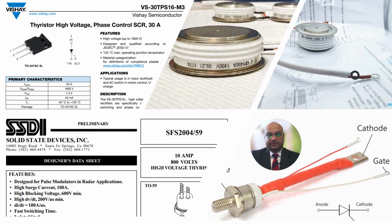Now let's see some of the data sheets, or how these thyristors look. As we have already seen, it can be a 3-terminal device as represented here by a make which is Vishay Semiconductor, and it is available in the form of 1600 volts, 20 amperes, and we can see these 3 terminals as anode, cathode and gate. Other devices here we can see in disk form, these are used for 1400 volts, and the name of the device is generally written over the device.